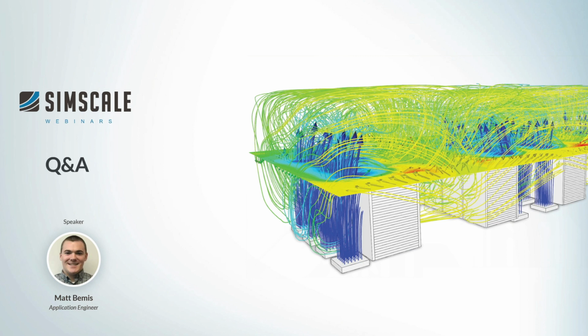I think lastly, can we get hard data? So points, if I have a sensor somewhere, can we actually get an exact value for temperature? You can drop in a CSV file of XYZ coordinates, we call them probe points, sometimes monitor points. You'll get a graph of temperature versus iteration. It's great for checking out convergence, and you can download that data and bring it into Excel and look at the agreement. So absolutely, I would encourage you to do so. And that wraps up the Q&A.